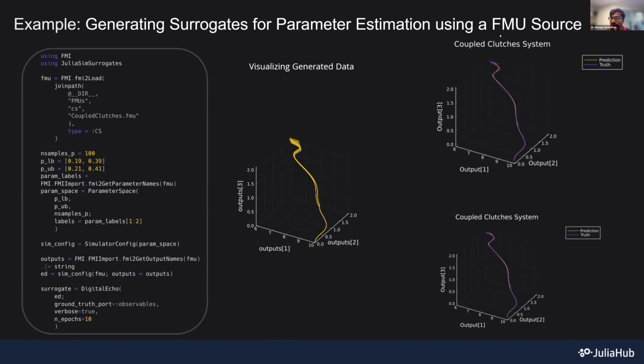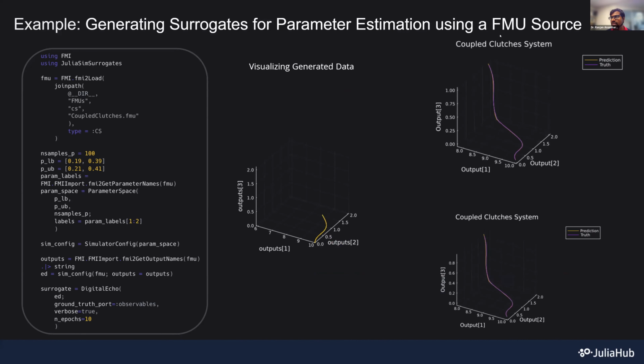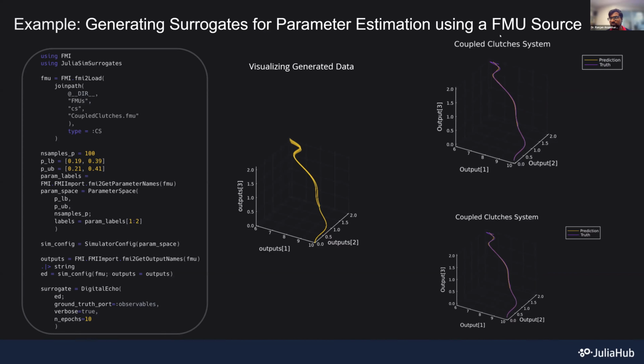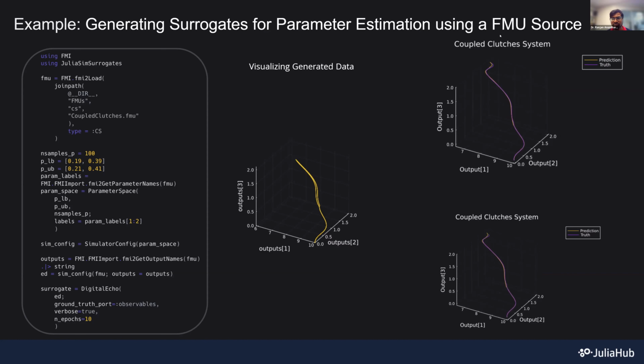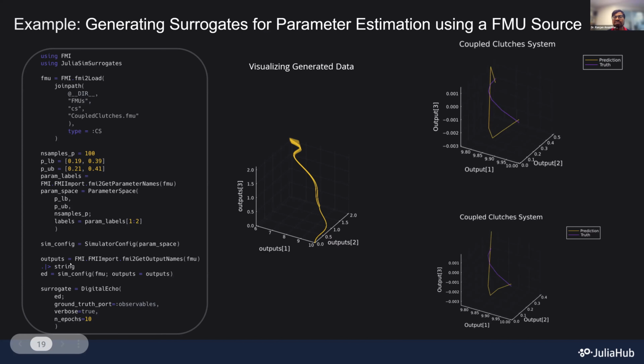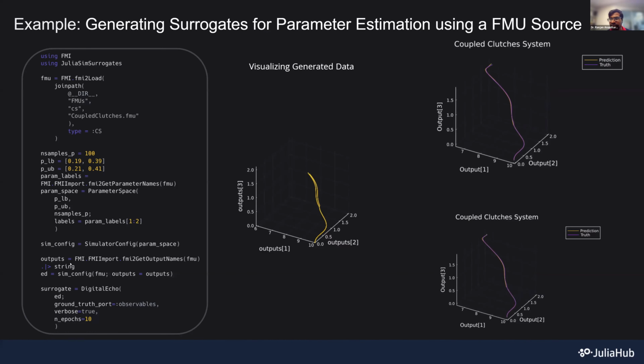It's a kind of binary that many simulators in the industry generate, and this is one of our inputs into our JuliaSim Surrogates framework. You can just take these black box models, simulate them a bunch of times and get dynamics, and you'll have a surrogate that matches that dynamics. So yes, absolutely, you can use black box models. Of course, when it's a black box model and you don't have much insight into the physics, it's a different set of trade-offs. But yes, the software does allow you to do that.